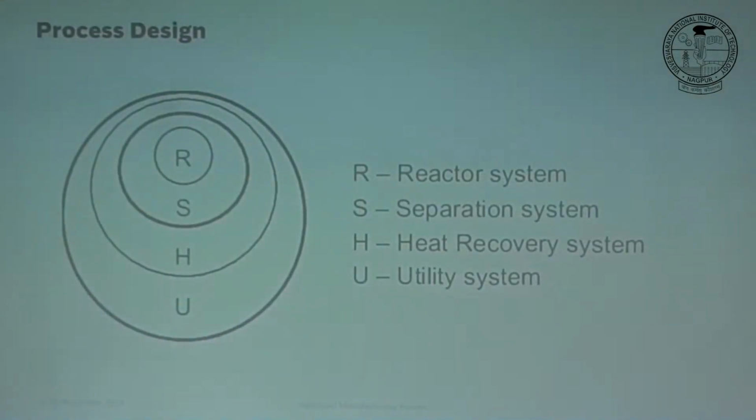Then we look into the heat balance. We already talked about the temperature. We have to supply heat to bring it from feed temperature to the operating temperature. Where is waste heat available? So we are talking about 850 as the operating temperature. That means the product stream is at 850. What do we do? We cannot supply hydrogen at 850 degrees. And then finally we will see if we have some heat left in the product stream. So what to do with this heat?